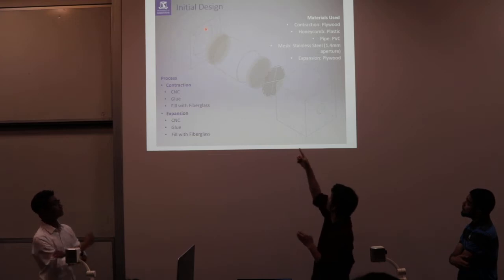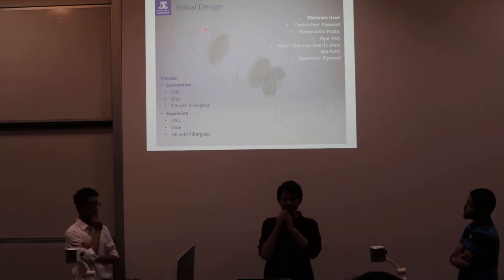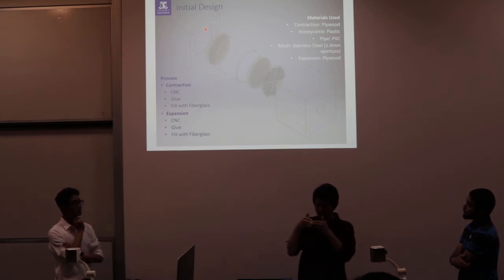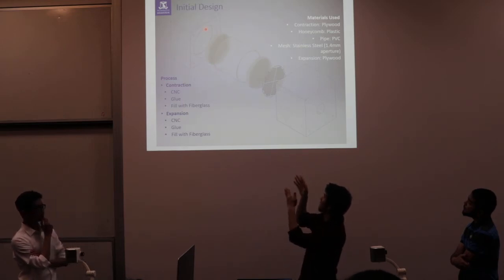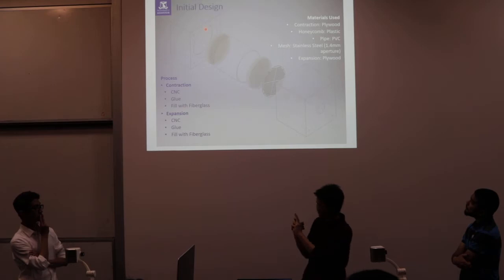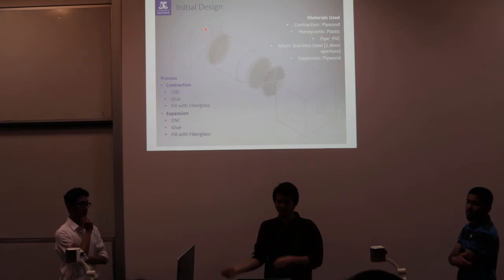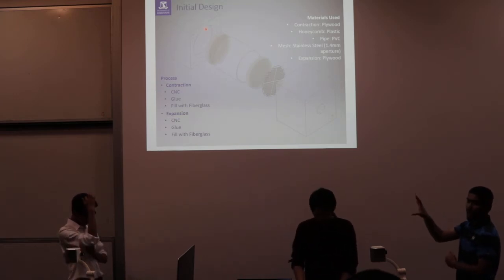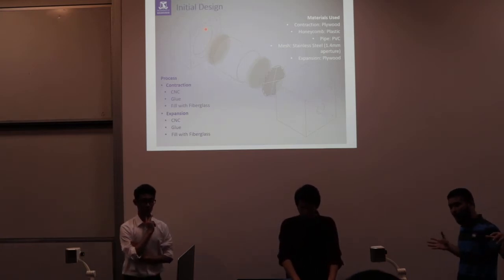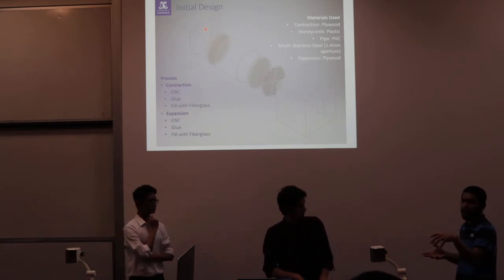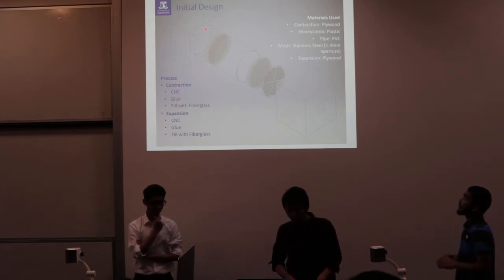Then later on, we use a metal mesh that has a smaller diameter than the honeycomb, so it will be squeezed again. Hopefully, by using these 3 sections of 2 honeycombs and 1 mesh, the eddies will be reduced. After the mesh itself, any existing eddies will be compressed because of the contraction. The contraction accelerates the flow, and when it accelerates the flow, it pretty much kills off any turbulence that is smaller than 0.1 millimeters, which is the size of the mesh.